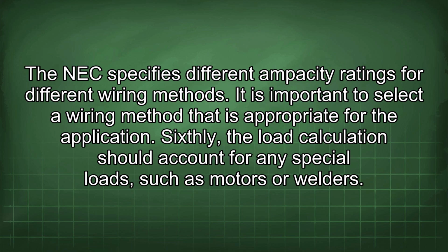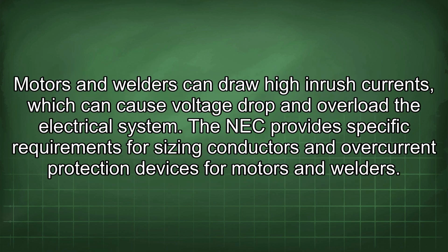Sixthly, the load calculation should account for any special loads, such as motors or welders. Motors and welders can draw high inrush currents, which can cause voltage drop and overload the electrical system. The NEC provides specific requirements for sizing conductors and overcurrent protection devices for motors and welders.